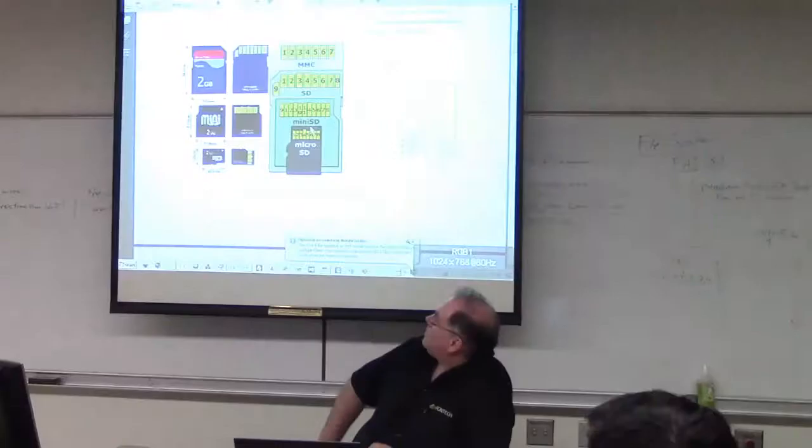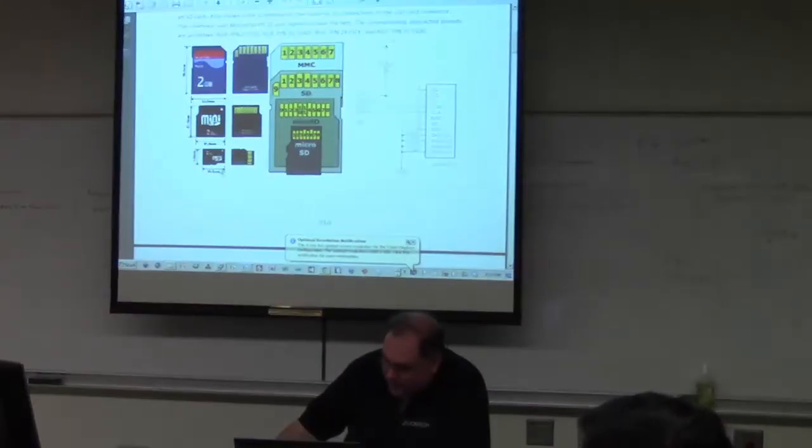It says SD cards can be addressed using at least 3 different communications protocols. The way we use it on our board, it uses SPI. There's a 4-bit communication mode that's a lot faster, but that, again, is patented by Microchip. If you look at some examples, there's the micro SD, a mini SD, and the regular SD. All of them have similar pinouts, and you can use SPI with all of them. SD, mini SD, micro SD.